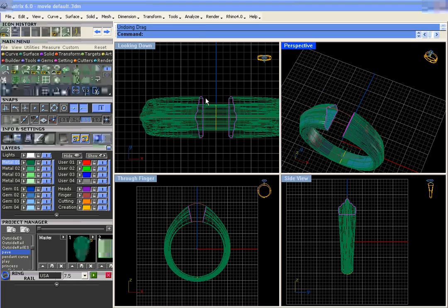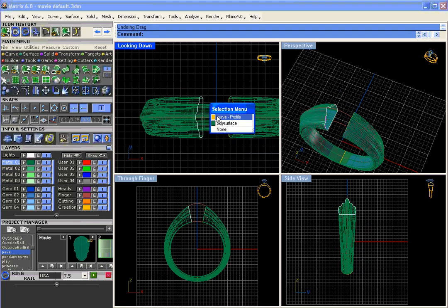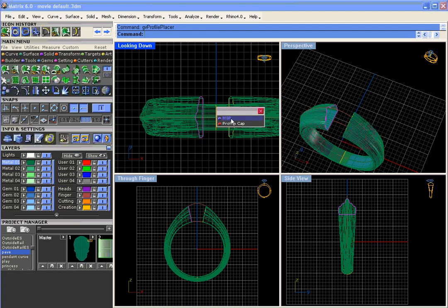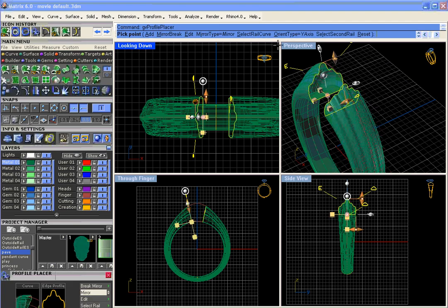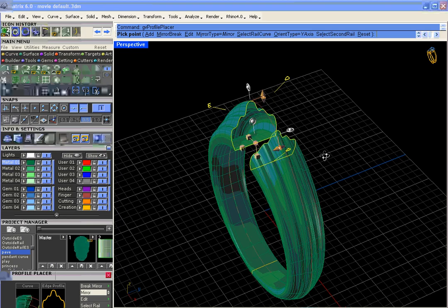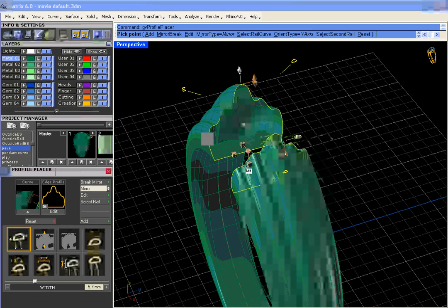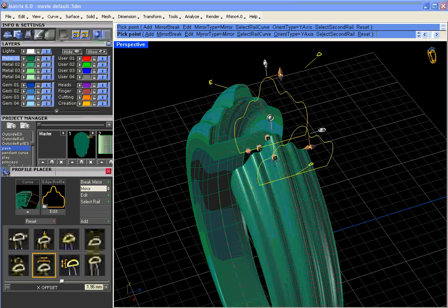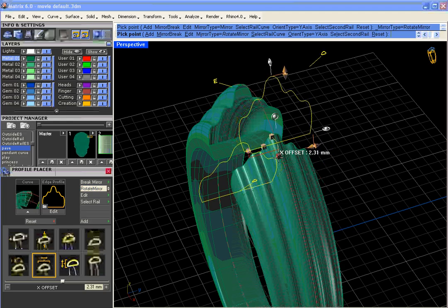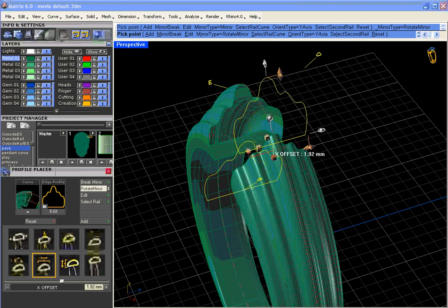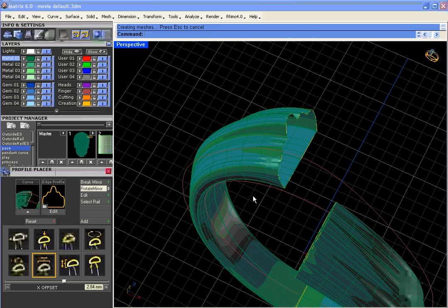The thing here is if you drag these, let's try this, F6, MSR, because I have these mirrored, when I drag one, the other one goes for the ride, okay? But if I toggle from mirror to mirror rotate, as I drag one, it actually does the opposite on the other side, which can be more desirable for this type of ring if you want it to be perfectly symmetric.